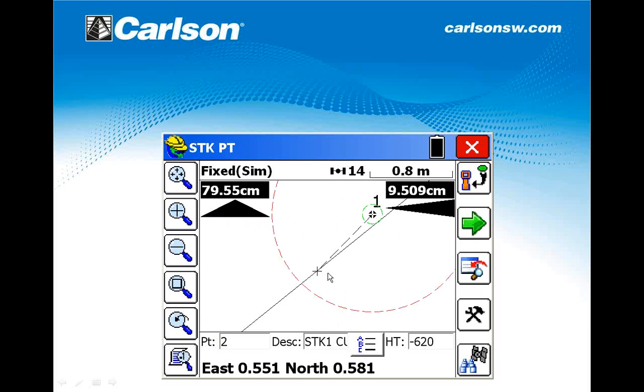This is now telling me 79 centimeter. Okay, in reality, how this works is that when you're approaching the point with a big arrow pointing you the direction and looking at the distance, you almost visualize the small area where the point should be, okay? So what I suggest is to look at that area on the ground and try to hit with the pole directly where you think the point is, right? So it will take you to some position normally within this 1 meter area, okay? You could set it to 1.5 to make it easier.